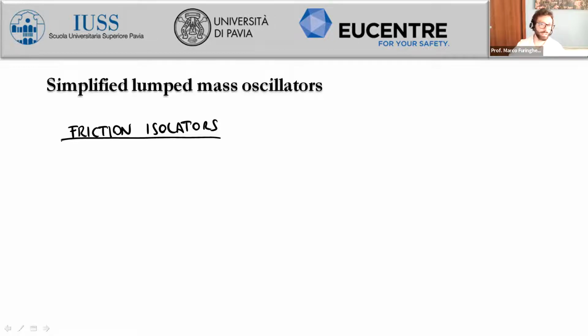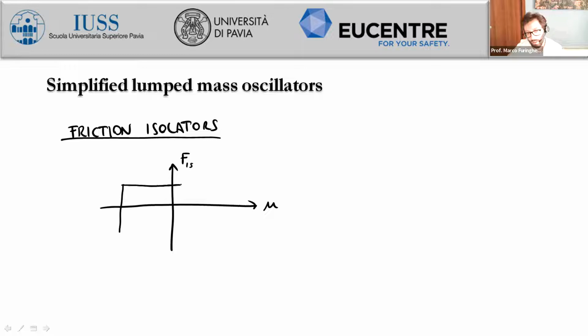So this means that we will start from the frictional response, and then we will also have the opportunity to add a linear recentering behavior, which is just a linear spring with respect to displacement. So we know that the theoretic response is something like this for frictional behavior. So let's consider the relative displacement and the force isolation. If this is just purely frictional response, we have something which has a rectangular shape. And how to model this?